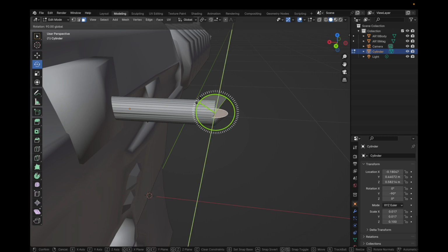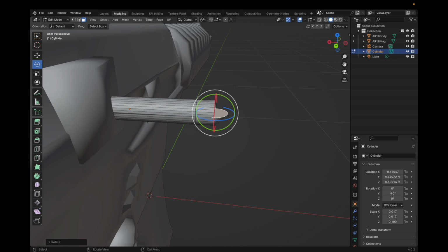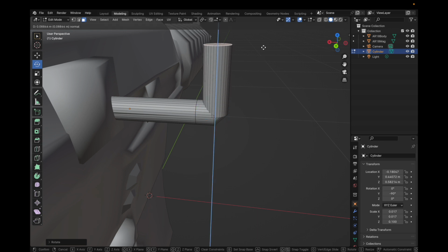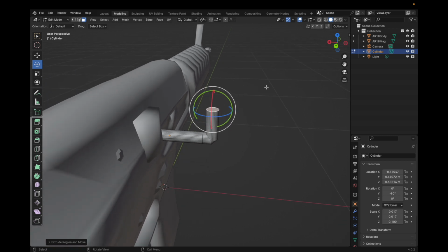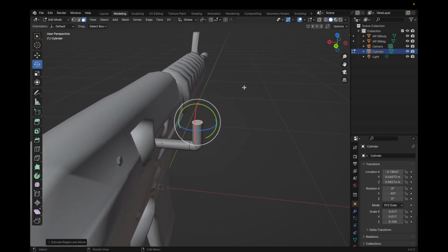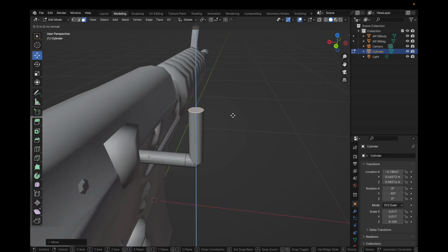So just rotate it all the way 90. Press E again and just keep extruding it. So this odd shape is finally becoming something. And then just continue extruding it. And then again, we need to do E, and this time we're going to pass in the number I have used last time as well. 1025. And then E and 0.